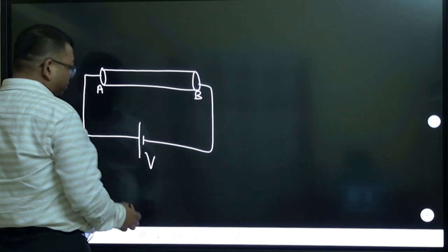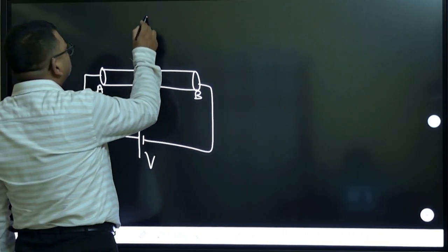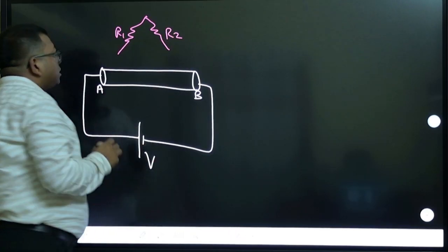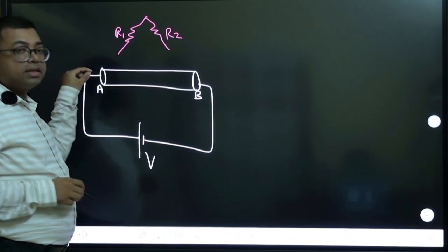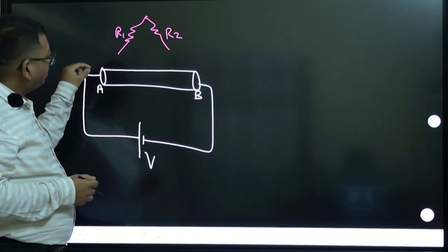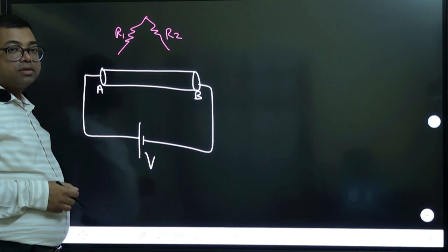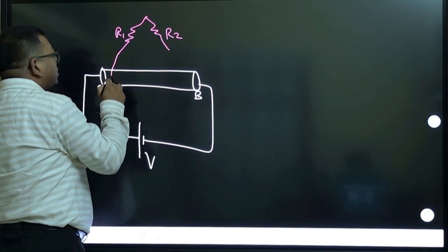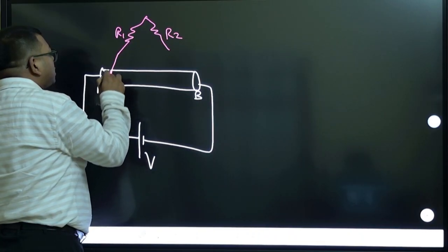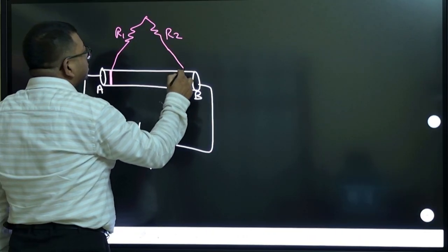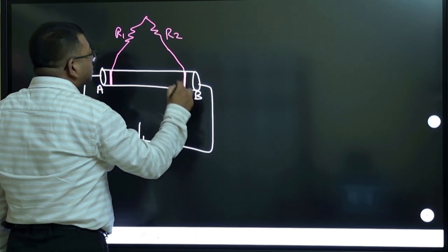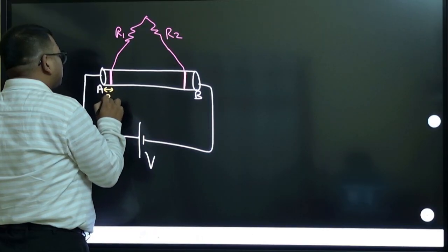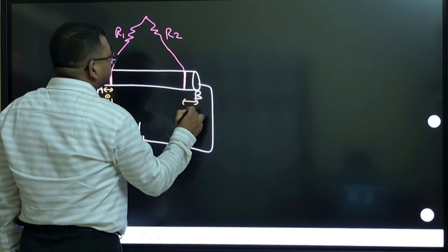Now when you are having a wire and you want to join this circuit, this resistance R1 and this resistance R2, the thing is that it is very difficult to join at the end. Practically, how will you join at this last end, right? Sometimes in the lab when you are joining, it may be joined somewhere here, and similarly this one will also be joined here. This is called end correction. This extra distance, let us say E1 and this distance E2, are called end corrections.